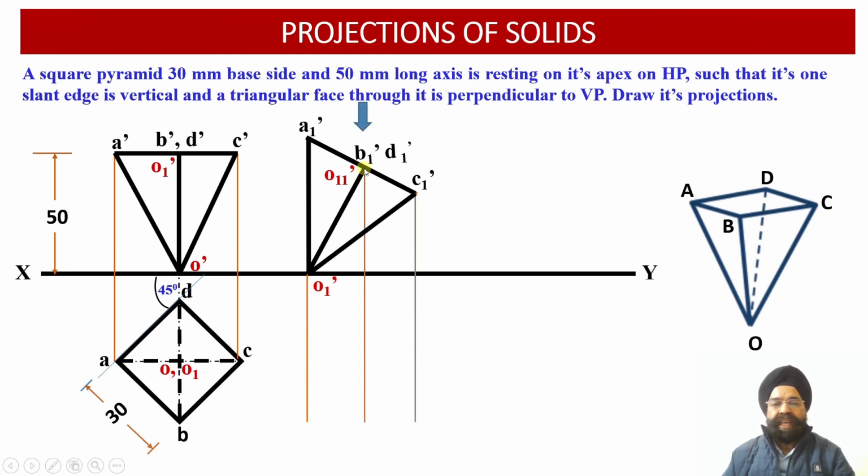So now we can see we have drawn the vertical projector lines through these 6 elevation projection points, and now we are going to draw the horizontal projection lines through the corresponding points from the plan projection view which we had obtained earlier, and wherever the intersection of the corresponding points is available, we will obtain the plan projection of the points in the top view projection onto the horizontal plane.